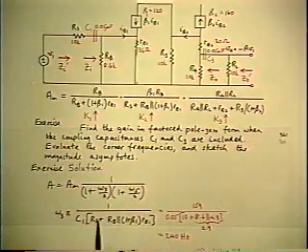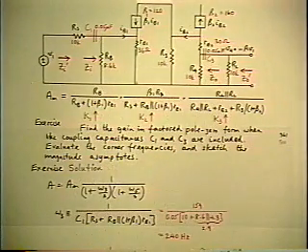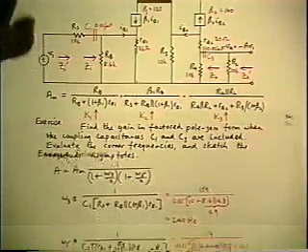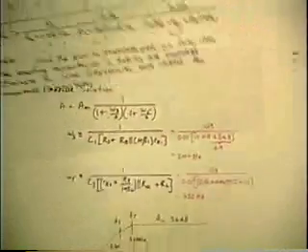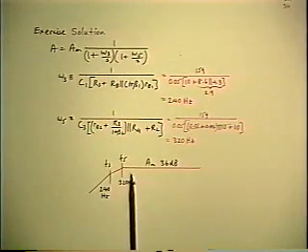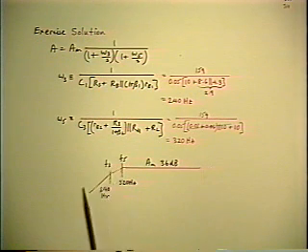So we've now obtained two inverted poles, one from each capacitor. Numerically, 240 Hertz and 320. So the frequency response is the reference gain of 36 dB and the inverted pole coming from each of those coupling capacitors.